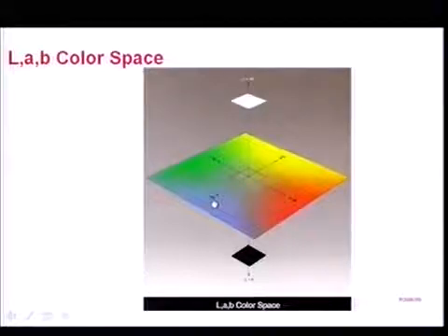Now, the goal of the de-inking and bleaching process is to get to the center, make the color as close as 0, A or B value. You do not want to move to negative, because what you are doing is, from pink color or red color, you are going to make the color green if you move to negative. You want to go to the center and go as high as possible to make white color paper.